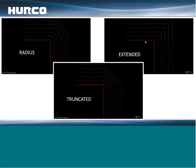We have extended here, which is basically going to do the same thing. It's going to offset all the tool path, and then it's just going to extend that tool path out to make that sharp corner. And then truncated is a little different. Once you offset out, it's just going to connect those tool paths with a line, so you end up with kind of a pyramid shape, a flat transition there. That's the parameter that deals with the corners, how you want those corners to turn out.